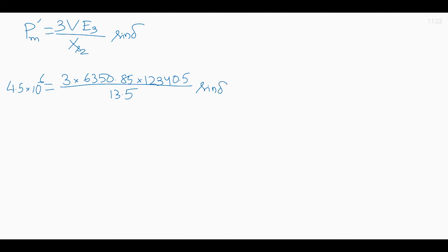So from this, sin delta is calculated as 0.258, and corresponding to this, load angle delta is 14.98 degree, and it is motoring operation.